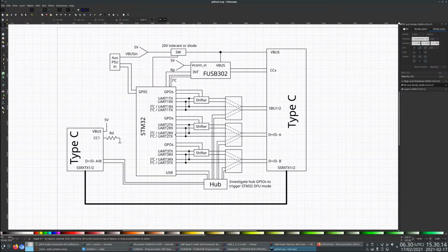Which does not mean that you can't plug both of these ends into the same host. You could totally plug this into the host as a debug port and then plug this into the host again and say this is now a device, an upstream-facing port, and you are now testing your own host's PD capabilities, or the other way around. You could even have the host try to supply itself with power, which I'm not sure about how the actual power routing would handle, but if it's happy to at least make the connection, then sure. Or you could give it external power here, plug this into a host, and plug this into the same host, and then charge your laptop and test. Nothing says they have to be different devices on either end. But role-wise, this is the debug port and this is the target port. I think that simplifies things.